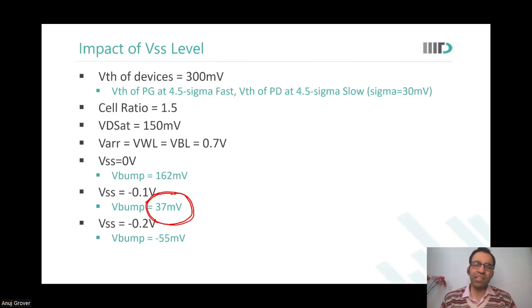It is just for ease that we say that this particular voltage is 0 volts. Do you realize, for the entire chip, I may keep VSS at 12 volts and VDD at 13.2 volts, and my circuit will work perfectly fine. All this is just about using something as a reference voltage. VSS is just about a reference voltage, when for your ease of calculations you want to call that reference voltage 0.